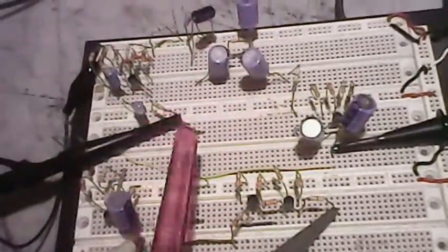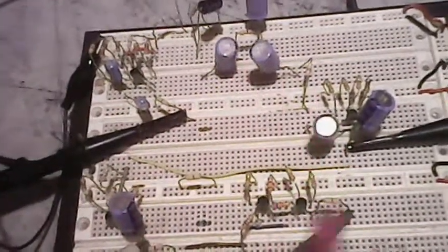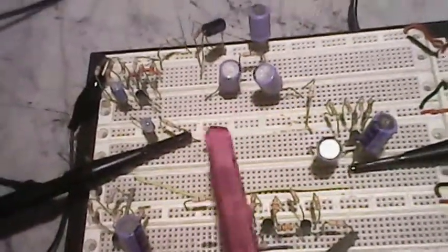Okay, so step 2 in this troubleshooting would be, again keeping the astable multivibrator separated from the rest of the circuitry as far as signal is concerned, checking with the oscilloscope this first amplifier here.